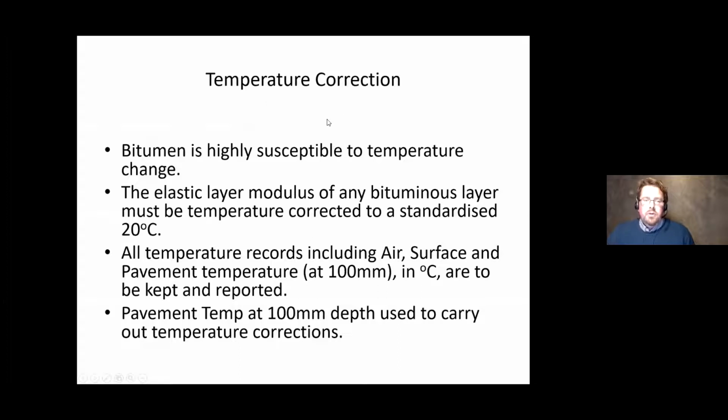Now, when we go back to looking at the FWD corrections data, once we have an idea of our pavement model, we've carried out our back calculation, and now we're determining our overlay or inlay. So we need to assess what the bitumen is doing. Be conscious when you're hiring an FWD that they're doing temperature correction, because bitumen is highly susceptible to temperature, and all designs are carried out based upon an ideal standardized laboratory temperature of 20 degrees Celsius.